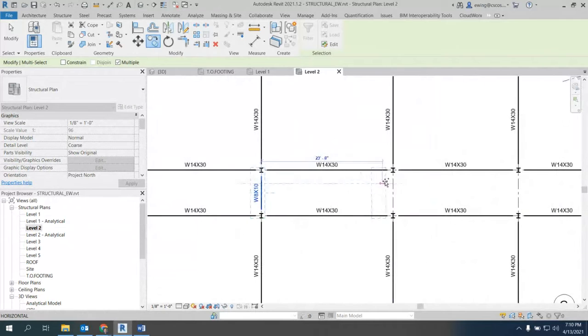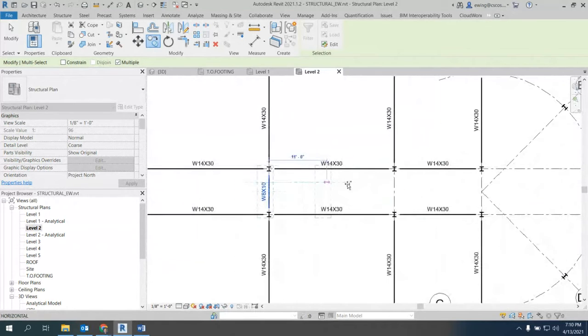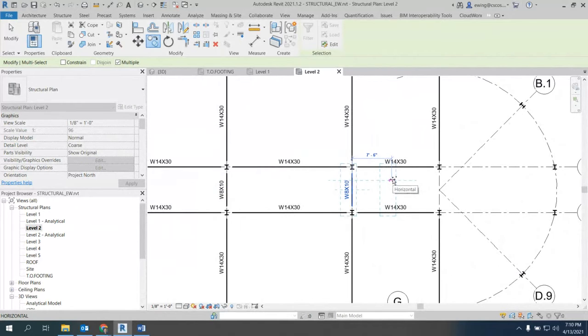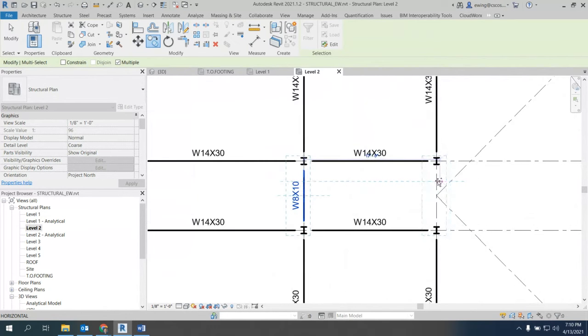And you'll see, because the line weight means something, the line weight on this means that it is actually analyzed as a girder. If you were to miss, that line weight would get real thin and it would analyze it as a joist.